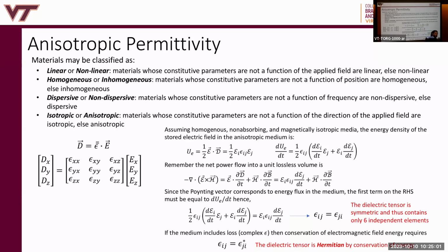And we expect that. Remember, in all of lecture 2, what did we study? Dispersion of permittivities, right? And we saw that there was strong frequency dependence. That strong frequency dependence allows us to design materials with negative permittivity, negative permeability, negative index of refraction, and get all this new phenomena, right? Dispersion is what we exploit a lot in guided wave phenomena.